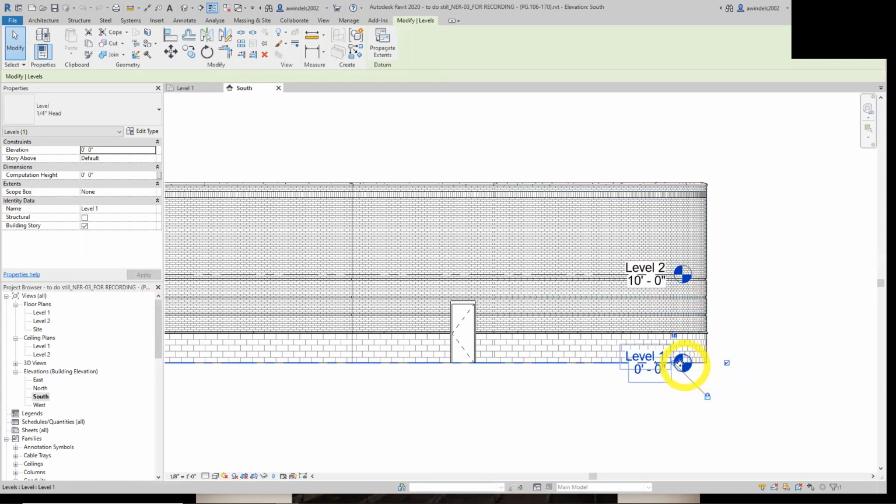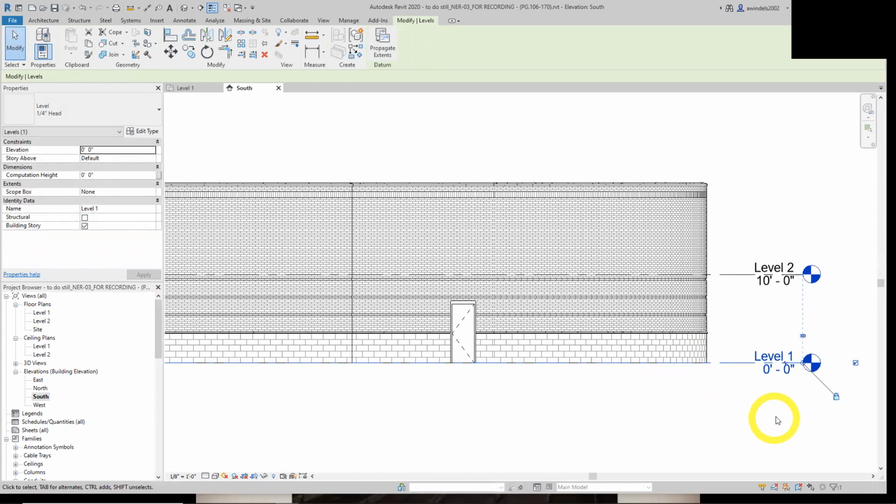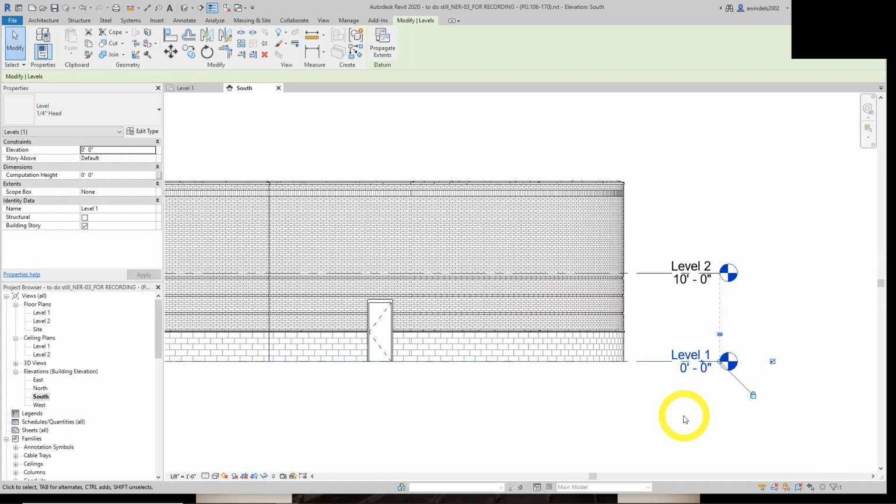So we're going to start by moving these out, and they'll move together if you don't unlock them, which is what we want. If you unlock them, you can move them one at a time. We'll see more of that later. If you hover over things in Revit, it says what it is, edit parameter, edit the level. It sometimes gives you hints, and it shows what it is in the status bar here as well.